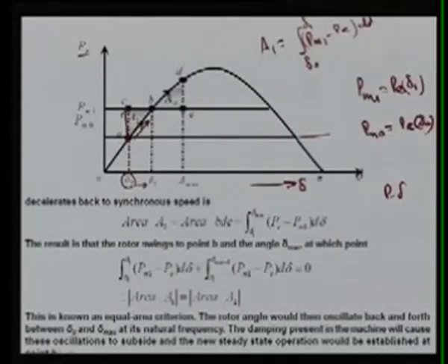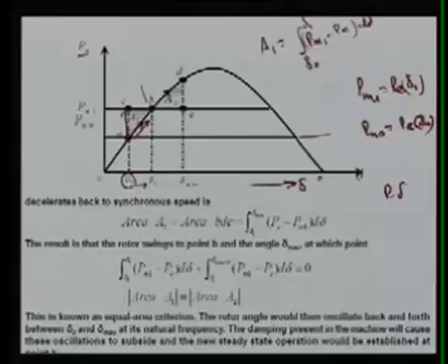Now what happens? From here it has to go here, and your rotor is now accelerating. But your rotor is oscillating at this point B, it is satisfied. But it is a machine oscillating, so what will happen? It will try to de-oscillate and it may go up to this point D. And here again, the speed of the machine will be the synchronous speed.